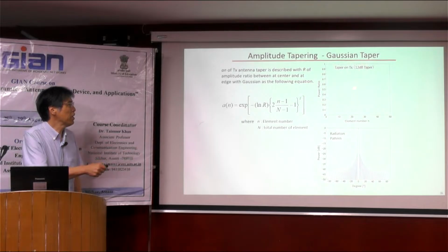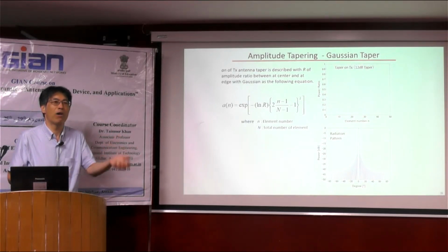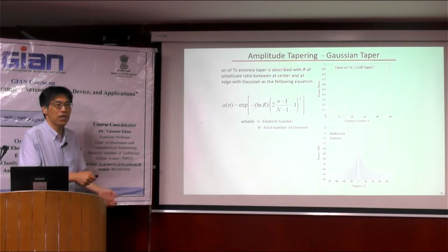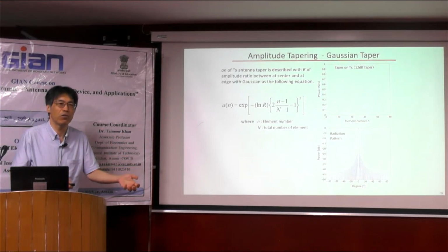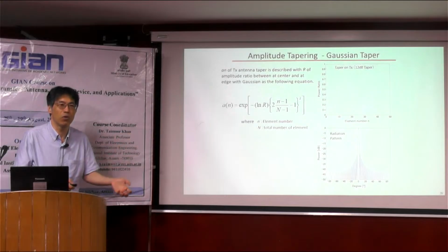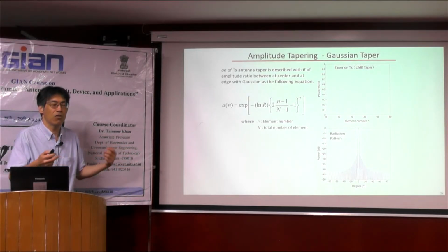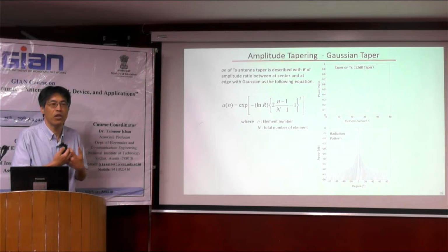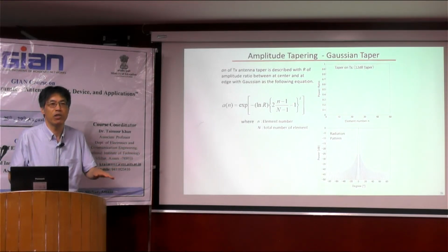At the center, for example, we must put a 10-watt power source. But at the edge of the transmitter, we must put a 1-watt or 0.1-watt power source. If we create a uniform transmitting antenna, we put the same powered transmitter only.